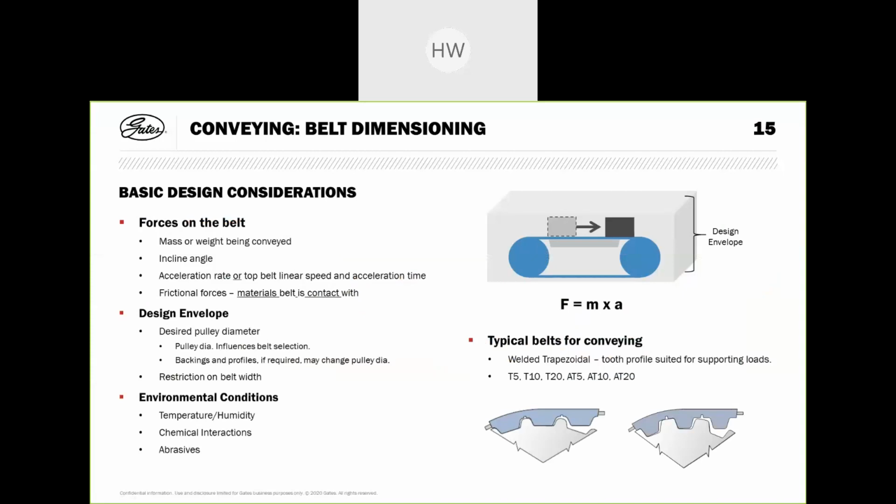And some frictional forces. Of course, the mass that is sitting on the back of the belt is a weight, and the belt is sliding over a slider bed, and we have to respect the friction force that appears between the belt and the slider bed.